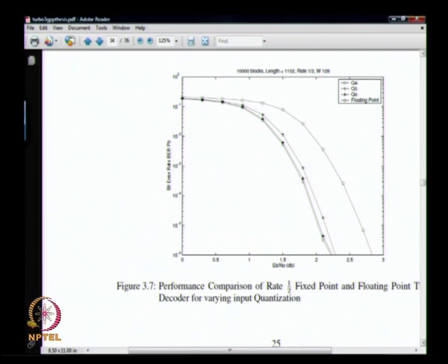If you remember the best convolutional code plots, they were at around 5 dB, 6 dB. So it is still like this huge 3 dB gap from the regular convolutional codes that you are using at rate half. And with Q6 quantization, as he calls it, I do not know exactly what Q6 is, but Q6 quantization is able to get very close to floating point. So you pick that as your point.